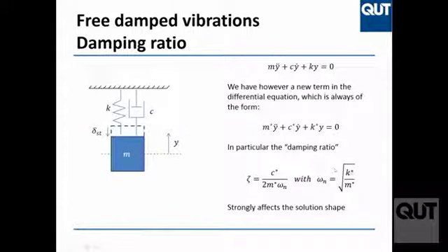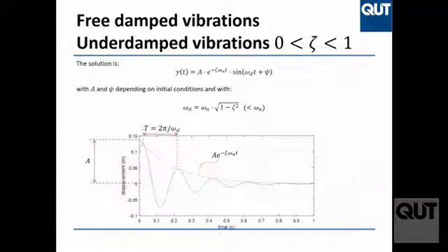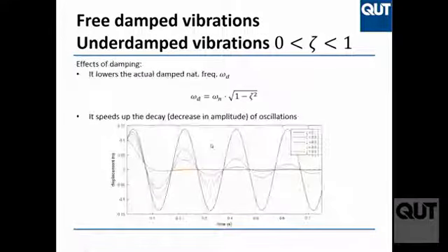Omega n is this value. K and m affect omega n only, and C will increase zeta. Bigger C, bigger zeta. Omega d then will follow, but who cares? We said if I want to keep omega n constant and increase zeta, then I increase C. So I increase C, and I get these values of zeta with the same omega n.